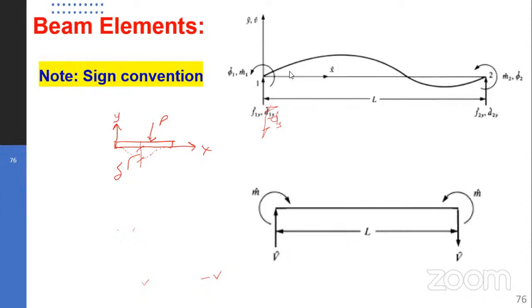So the first is showing positive components. This is the x-axis. So this is showing a positive moment. You see, the positive moments are counterclockwise. For this to be a positive rotation, it is bending on the bottom lower part, and for this to be positive on this side, the rotation has to be above the x-axis so that it will be in the counterclockwise direction, positive.